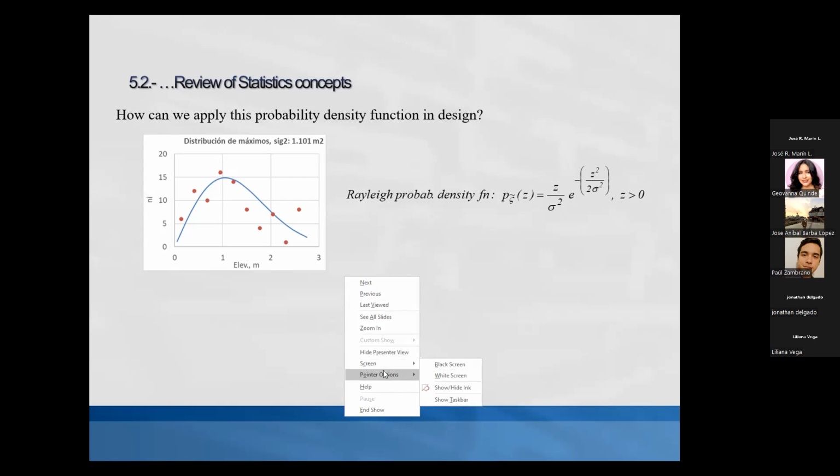Maybe you remember, and I'll try to remember for the next session, that in the introduction of the classification rules, you can read that the rules were developed with a probability of exceedance of 10 to the minus 8. What do they mean? Let's suppose that this is not wave elevation but the vertical bending moment on the ship, on the midship section.